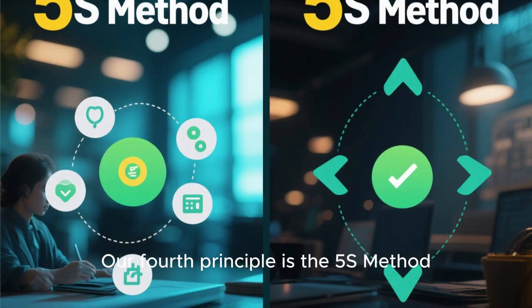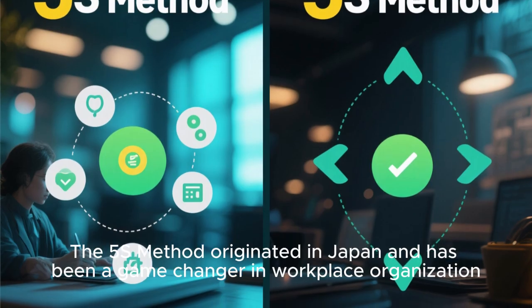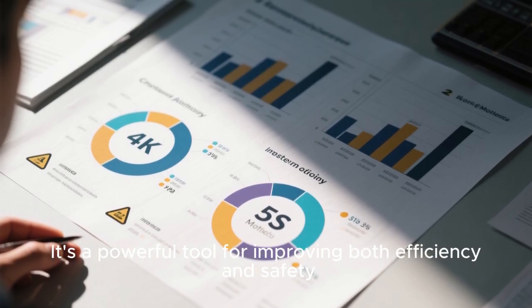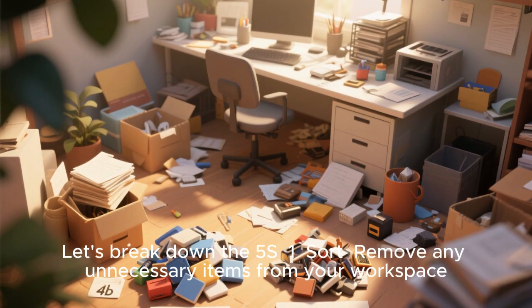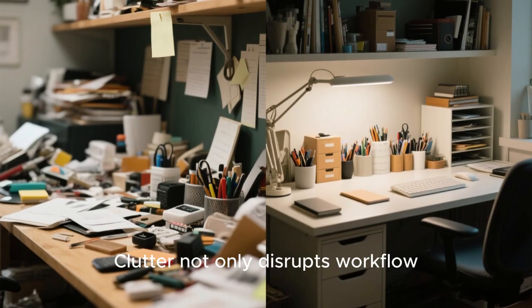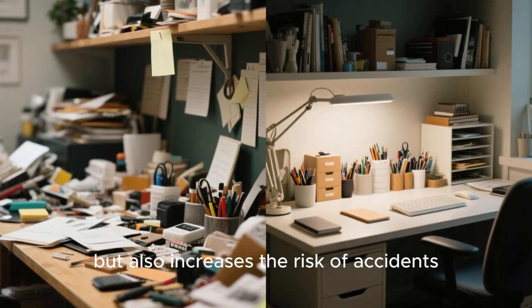Our fourth principle is the 5S method. The 5S method originated in Japan and has been a game changer in workplace organization. It's a powerful tool for improving both efficiency and safety. Let's break down the 5S. 1. Sort. Remove any unnecessary items from your workspace. Clutter not only disrupts workflow, but also increases the risk of accidents.